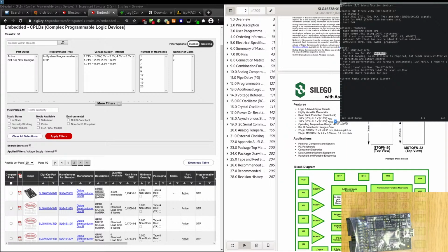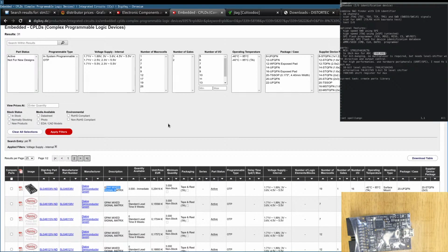The issue is that VDD2 should be lower than VDD, and not every combination works where on one side I have 3.3 volts and on the other side I have 1.8 to 5 volts. So I cannot use this PLD or CPLD, and I didn't find any CPLD which was taking 1.8 volt to 5.5 volt on one side and was giving out 3.3 volts on the other side. I still needed level translators and analog multiplexers.